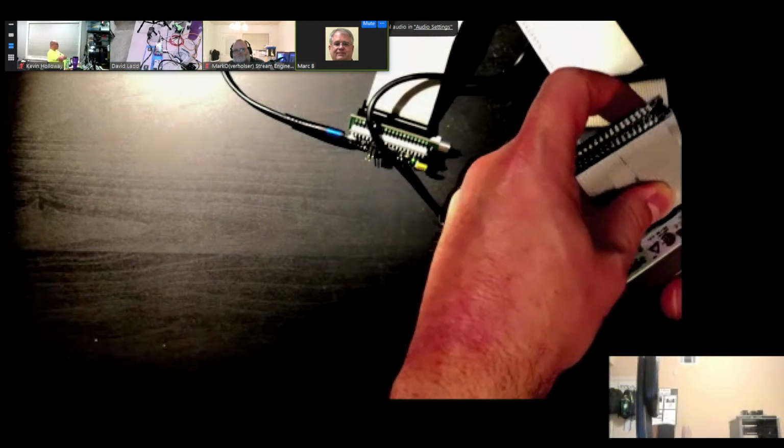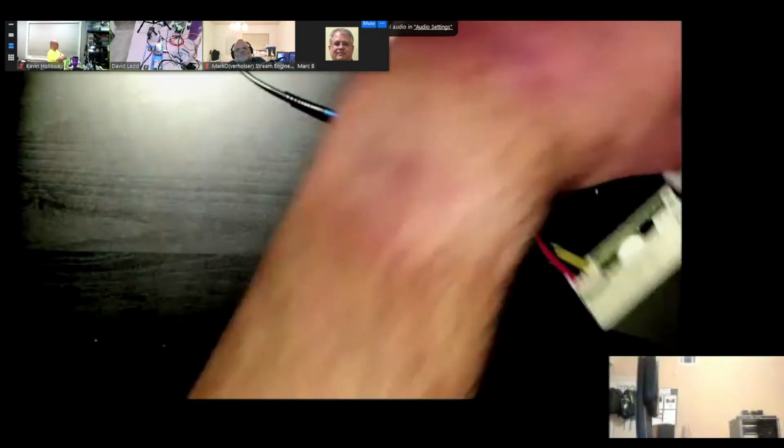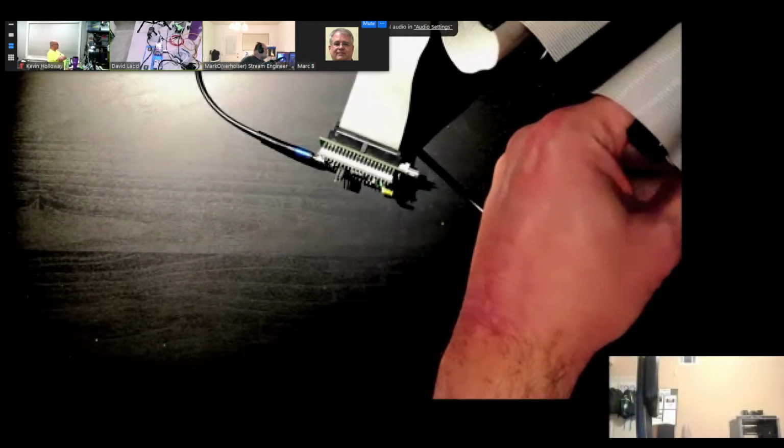Yeah, if you power the floppy drive and you've got it backwards, it'll immediately turn on. The light's lighting up. That's backwards. Yep, I plugged it in, the light's lighting up, it's connected backwards. Let's turn it around. That's one nice thing about the floppy cables. I want to mark that for future use.